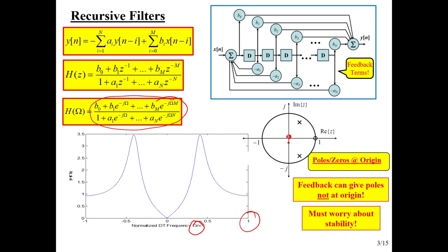I like that because MATLAB will give you nice mile markers, so I can see where pi over 2 is and so forth. If you plot it just versus omega, MATLAB is going to give you weird hash marks in weird places that don't make any sense. So that's why I do that. And then I'm showing the magnitude of the frequency response. Sometimes we'll be interested in the phase response, but more often than not, we're interested in the magnitude plot.